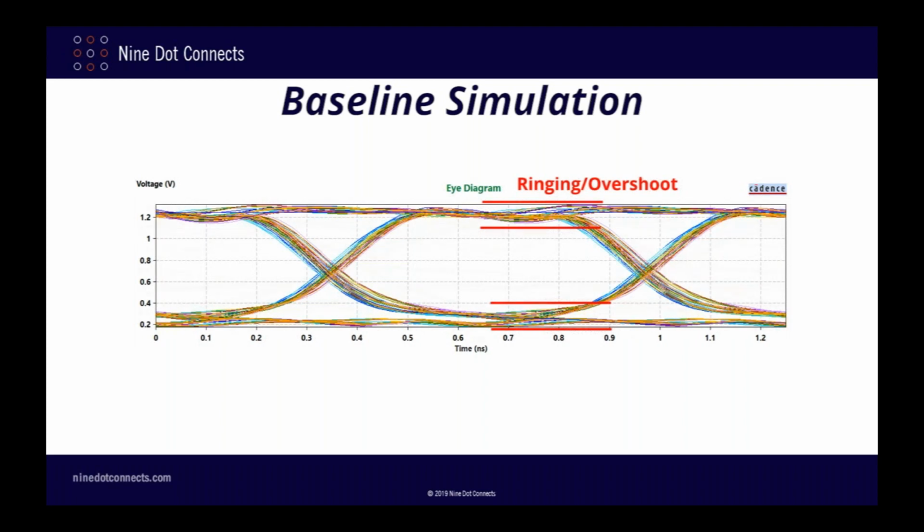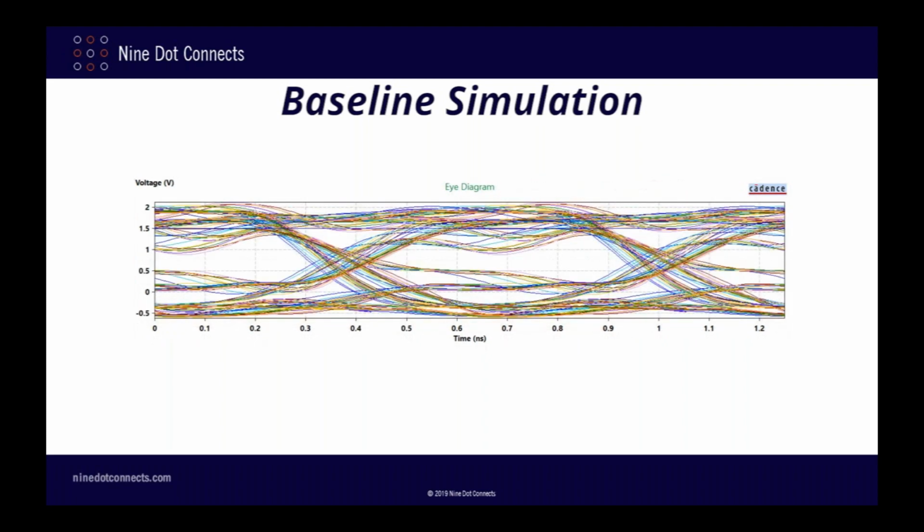Here is the eye diagram of the result. Remember, everything about this is the same except for the no on-die termination setting. Pretty dramatic difference, huh? As we see, there's a lot more ringing and overshoot, the transitions are noisier and the jitter is much worse, and as a result, the eye opening is almost non-existent. I'm pretty sure this would not work in the real world.